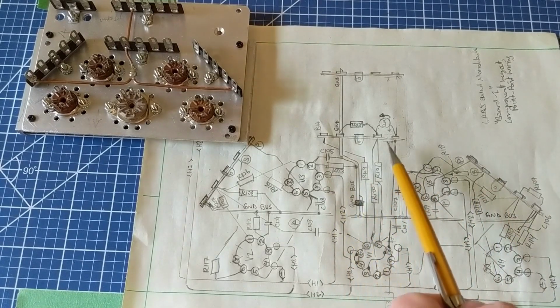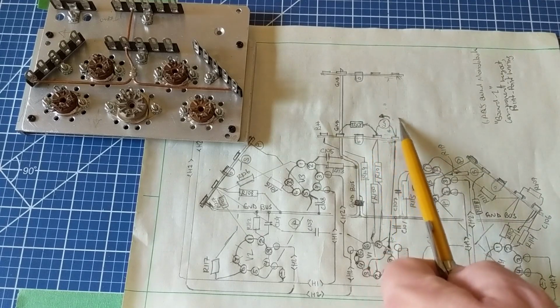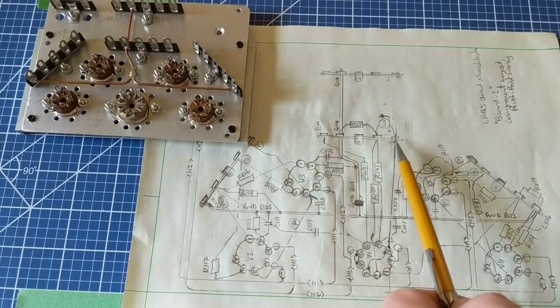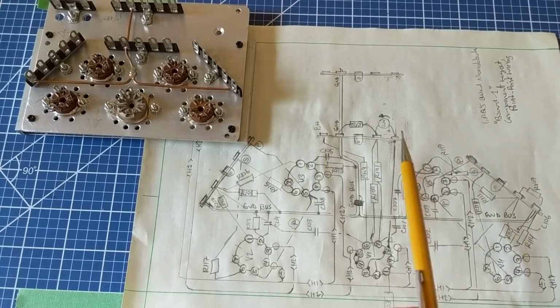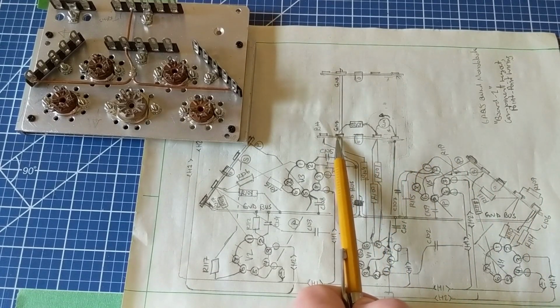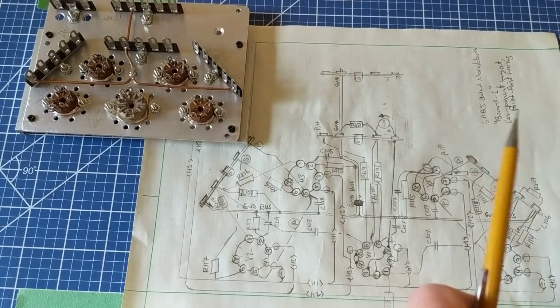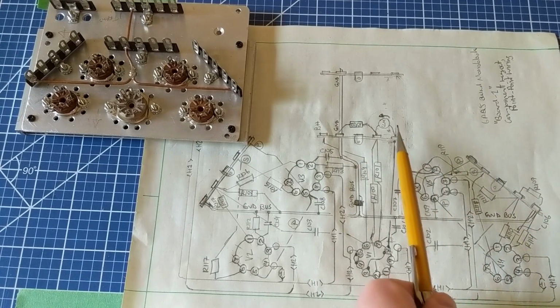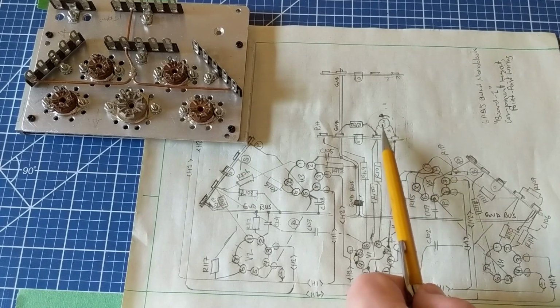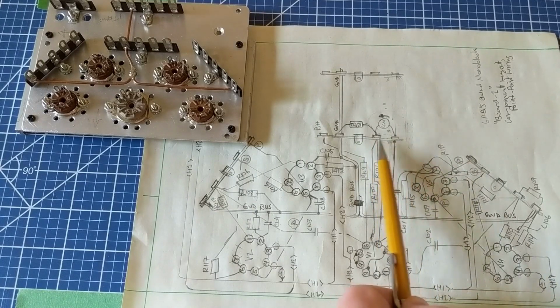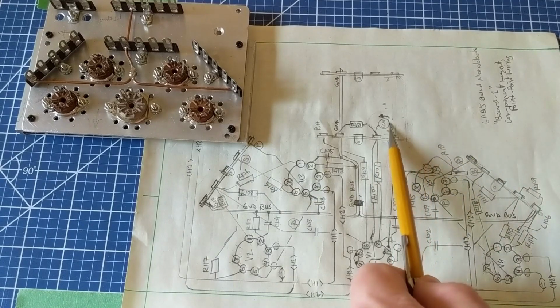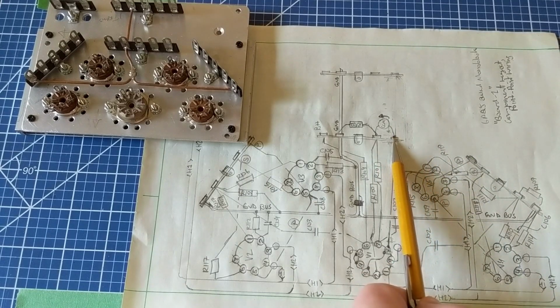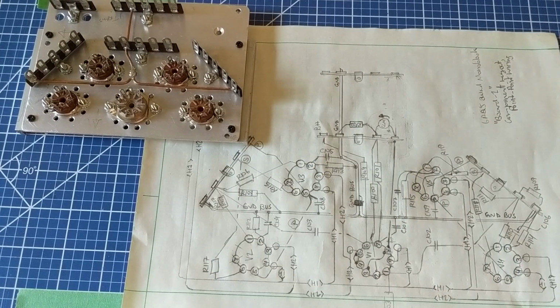I also needed to find a place for the constant current source, so I put that in here. It requires 3 tie points, one of them being ground. So I just have the ground here, the resistor, and then there's going to be, let's see now. No, I stand corrected. The constant current source really only needs 2 tie points, not 3. Because the adjustment leg is actually tied to an existing resistor that is on the output facing up towards the cathodes of the phase inverter.